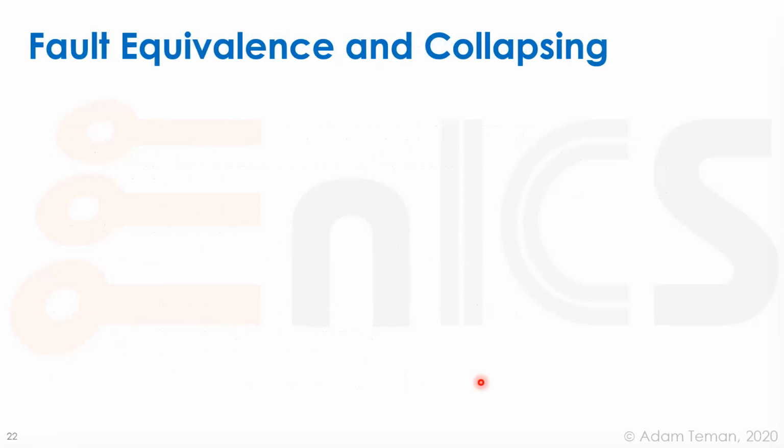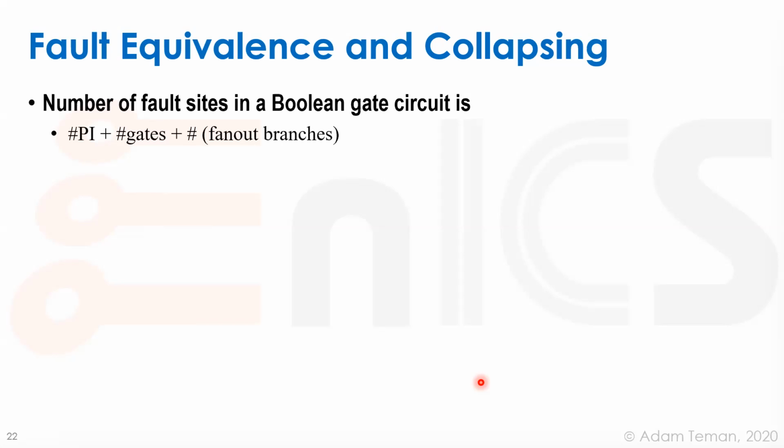So what I basically said here is that you can have different patterns that if you look and observe, if you applied a certain vector at the input to a circuit and at the output you see either a 1 or a 0, you can know that this failure and this failure and this failure didn't happen. So that's called collapsing. We want to see if we can use fewer paths than we would actually need to check each and every one of these failures.